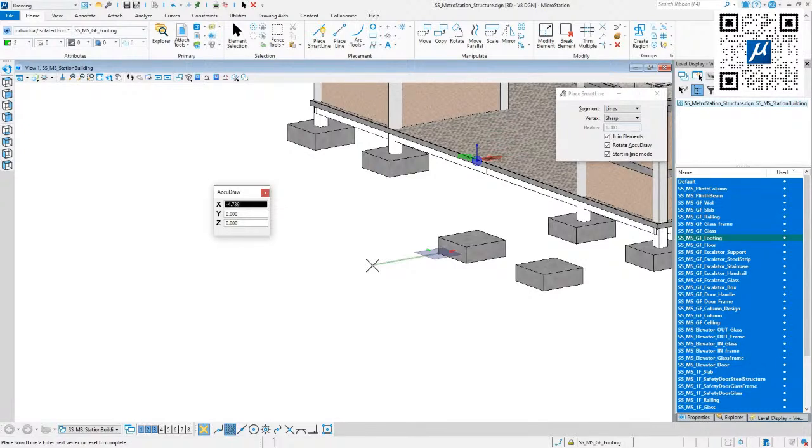It's F for front view and S for side view. Very easy to remember. So if I want to go along the floor level, I go to top view, and then I can draw my line right here, to the left maybe. And that's what I get with this rotation. Very flexible. I have another example prepared that I'd like to show you in a minute where you can use this.